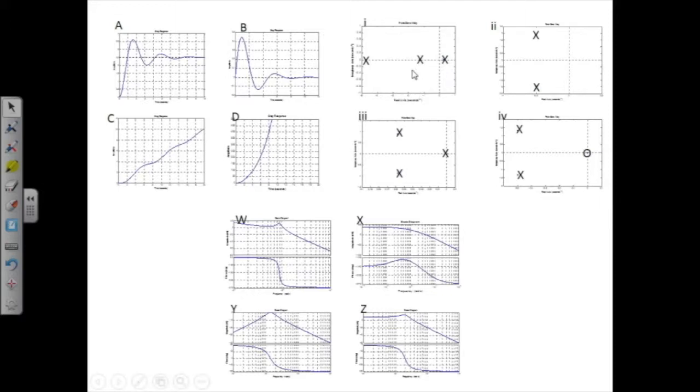So where were we? It's not 1, it's not 2, we've done that one, so it's 3. So what's causing this? These are all step responses, aren't they? So what's causing this upward slope here, do you reckon? Okay, there's an integrator involved in this transfer function. And if you integrate a step, it's just a constant once you pass the initial bit. So if you integrate a constant, this is a unit step, so integrating 1 with respect to time, you get 1t. And if you draw 1t, what you get is a line going up there with a slope of 1.